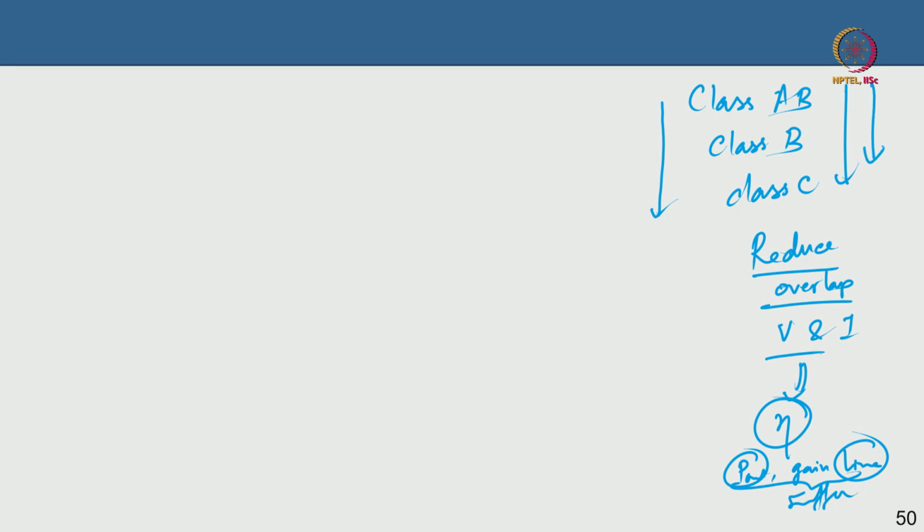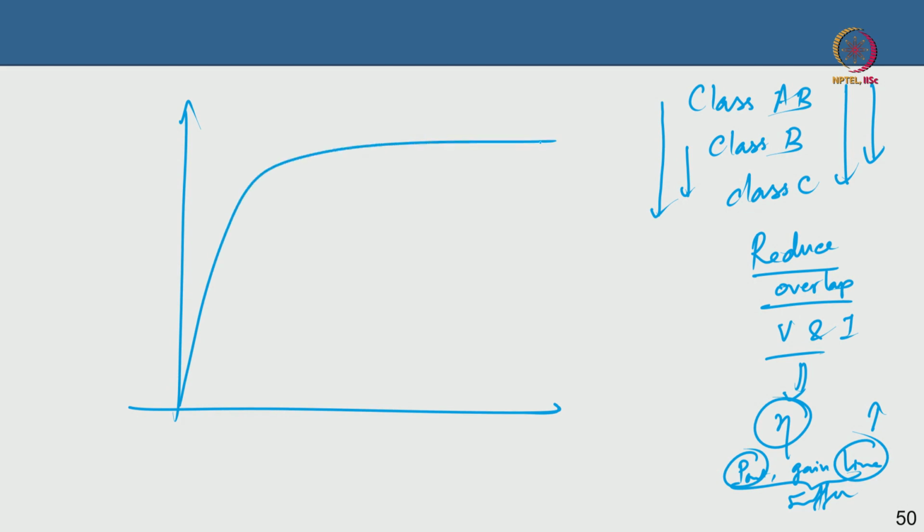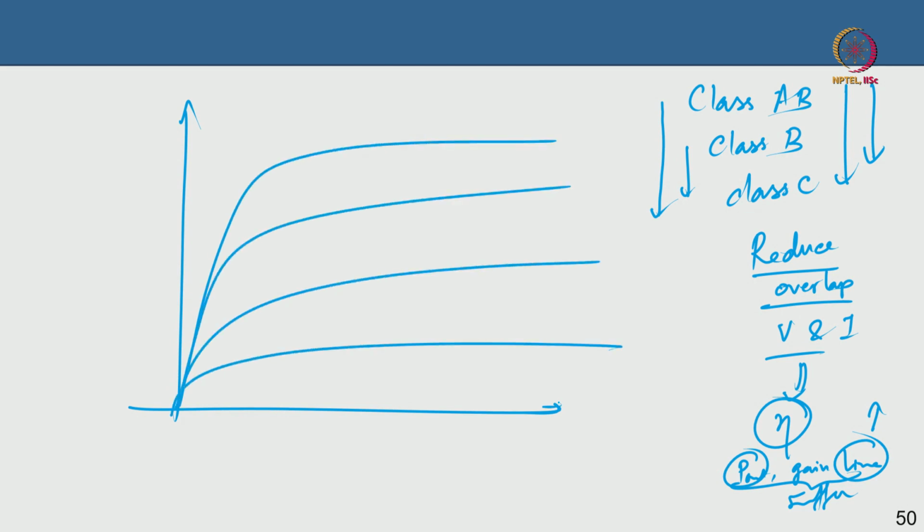At the system level, you can introduce some blocks, like a digital pre-distortion block, to improve the linearity, for instance. It adds to the complexity, but there is no way out. With higher efficiency, you have to go to higher classes of operation. So, when I say higher class of operation, if you recall the IV characteristics here, I told you the load line is this for class A.